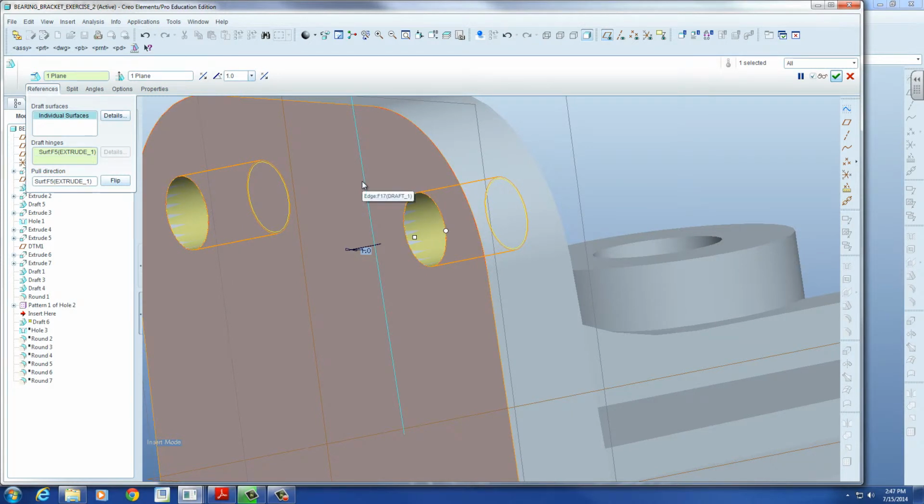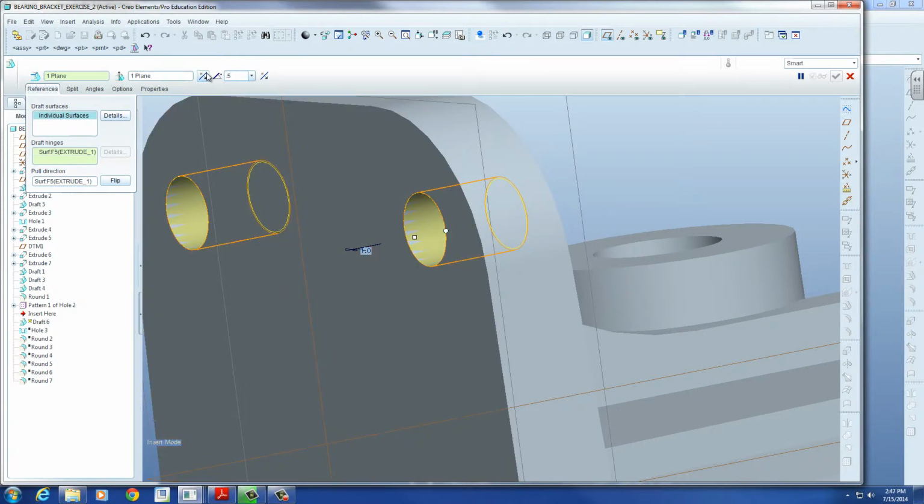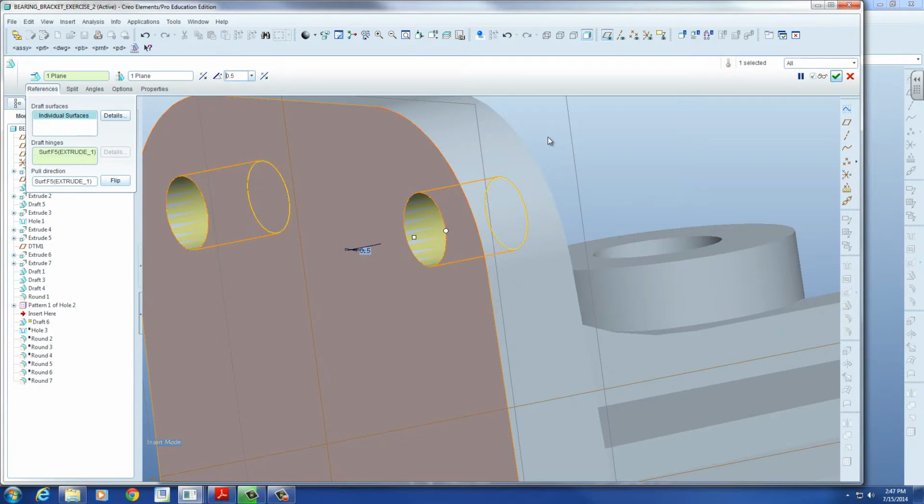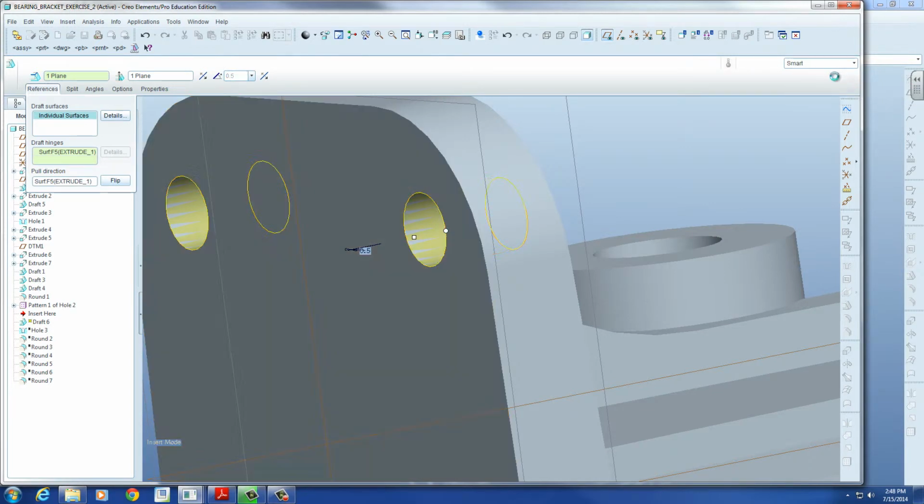We also said in our notes that we only needed a half degree on these holes. 1/2 degree, so that's going to help us. Good. So what we have to look at is what is the smallest diameter of this, and make sure that we have the proper clearance. So we would increase the size of the hole to get the clearance from the screw that we want in the clearance hole.